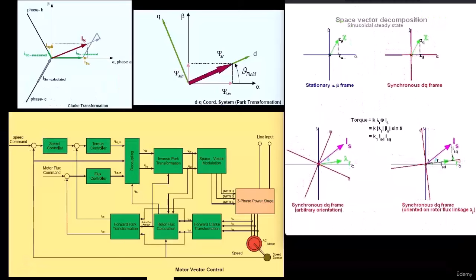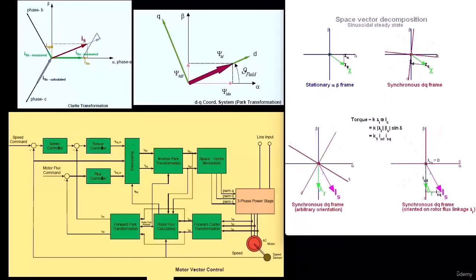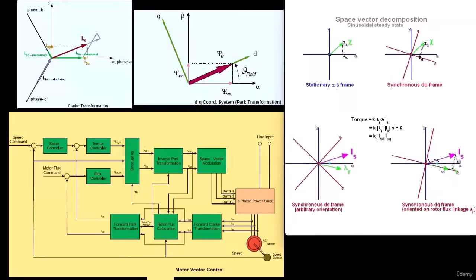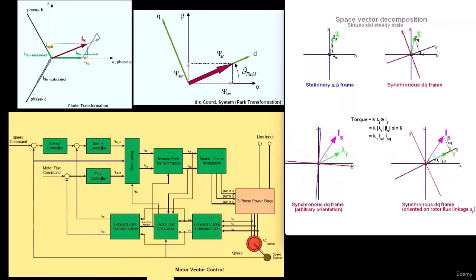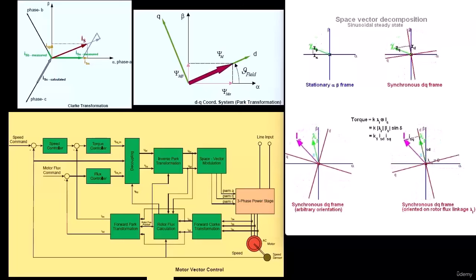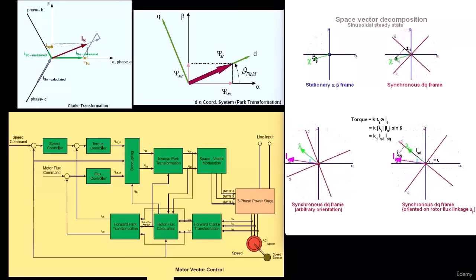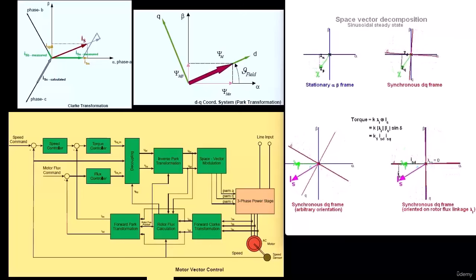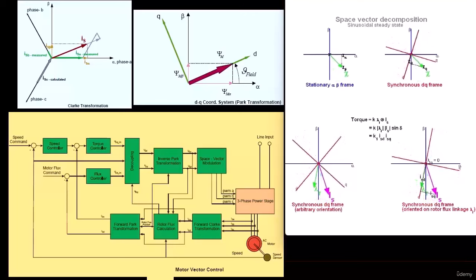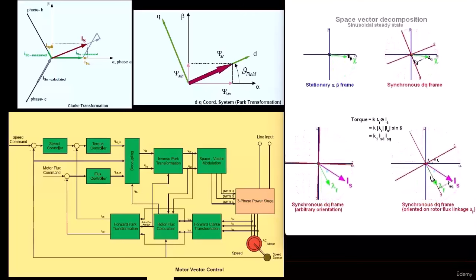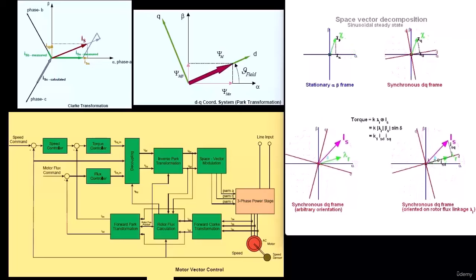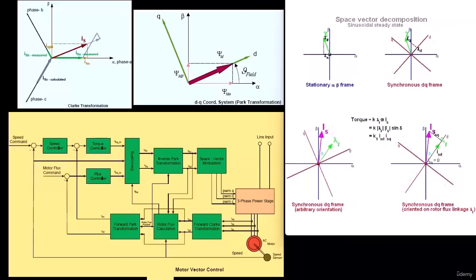The creation of mathematical models of AC drives is the first step in the development and implementation of control systems. In this chapter, mathematical models of machine drives are presented in a uniform way, firstly by using a space vector description of physical quantities such as voltage, current, and flux, and secondly by converting the space vector based model into different reference frames. The asynchronous machine, or the induction machine, is used as an example to illustrate in detail how its dynamic model is constructed.